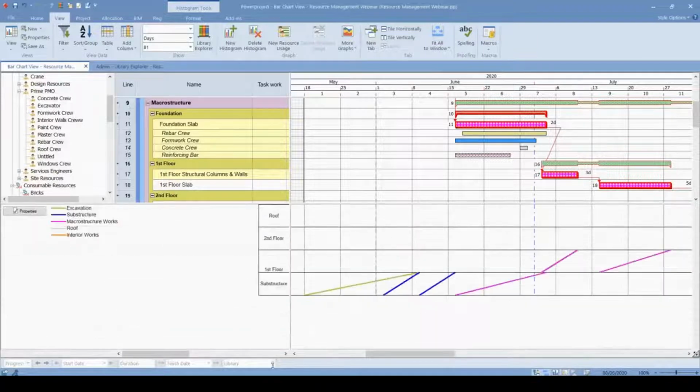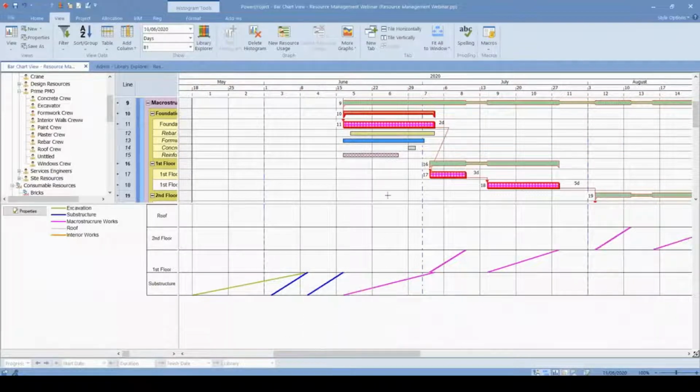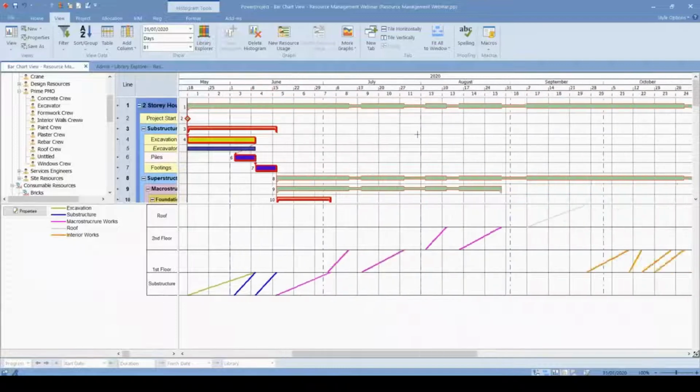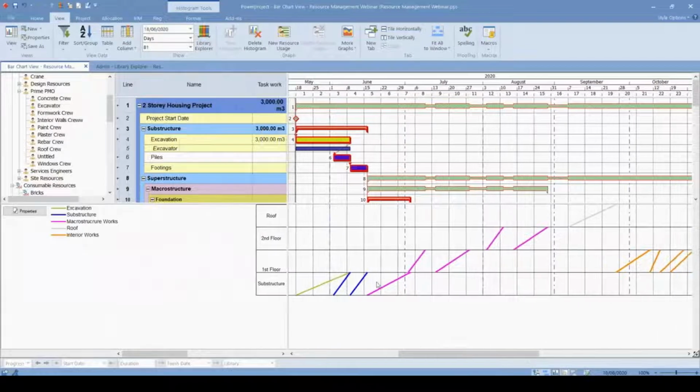The other thing is we can use our line of balance charts to determine our crew flow, so we can see all the resources allocated in the activities, to make sure that every crew, once they finish their work in one location, has their waiting times eliminated or minimized.